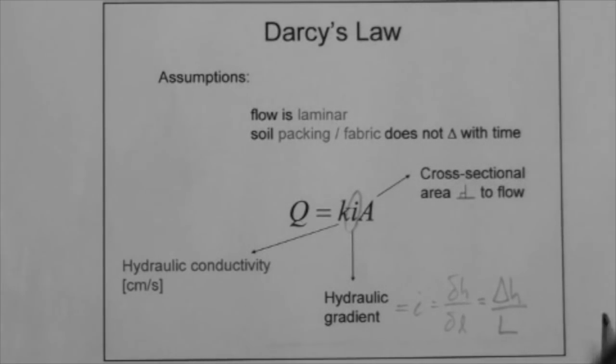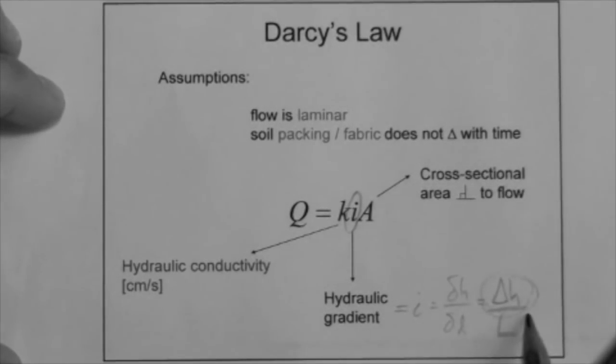So now we have a new definition of hydraulic gradient that you have to know. It's not a new definition, it's a modified definition, which is the change in head, or the head loss, as well as the total head difference. You can call it whatever you want, as long as you call it one of those three: head difference, head loss, or difference in total head, divided by the length over which the head is lost. Remember that head is energy. As fluid flows through a soil, it loses energy because it's grinding against the grains. That's why we call this head loss.